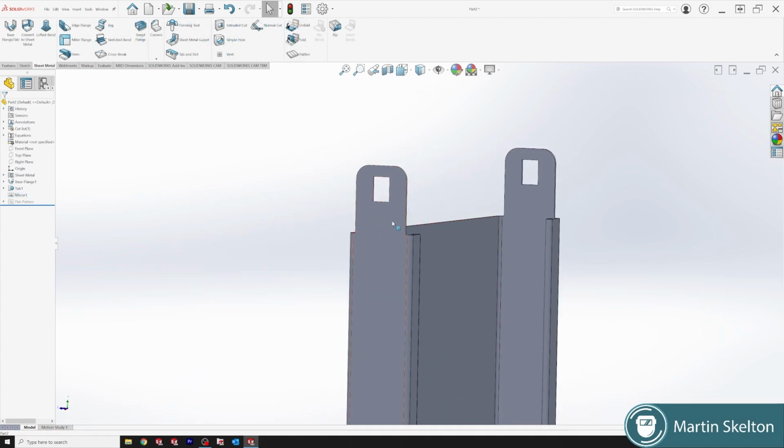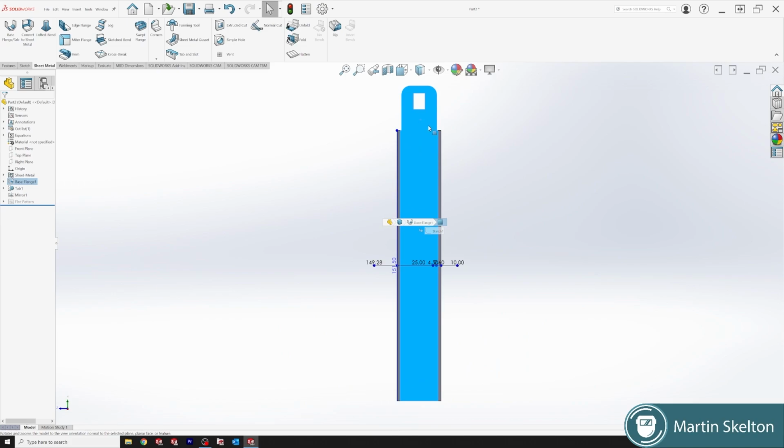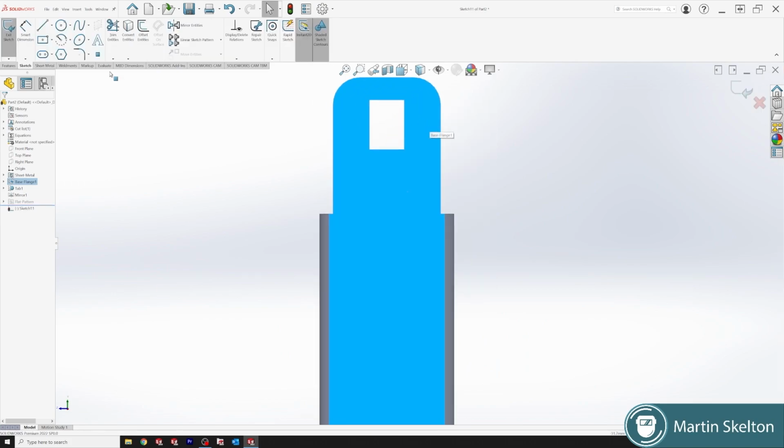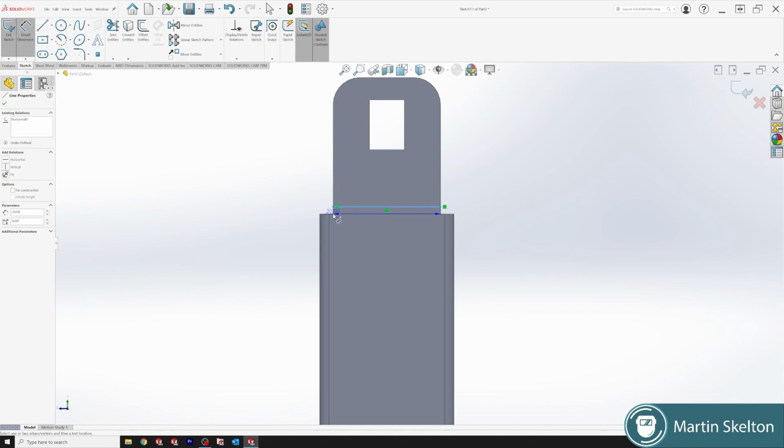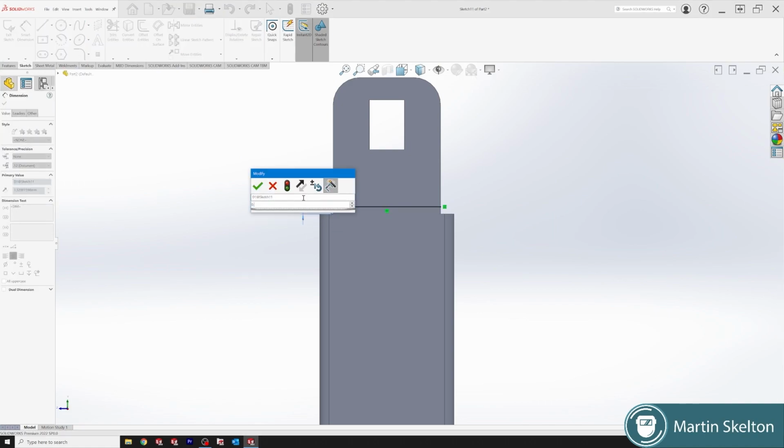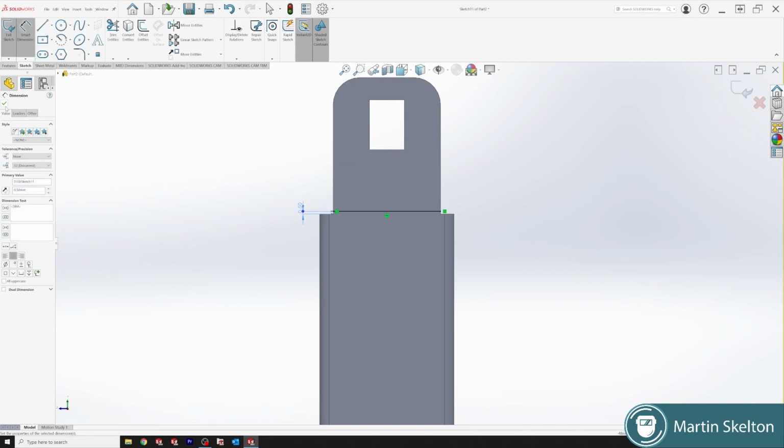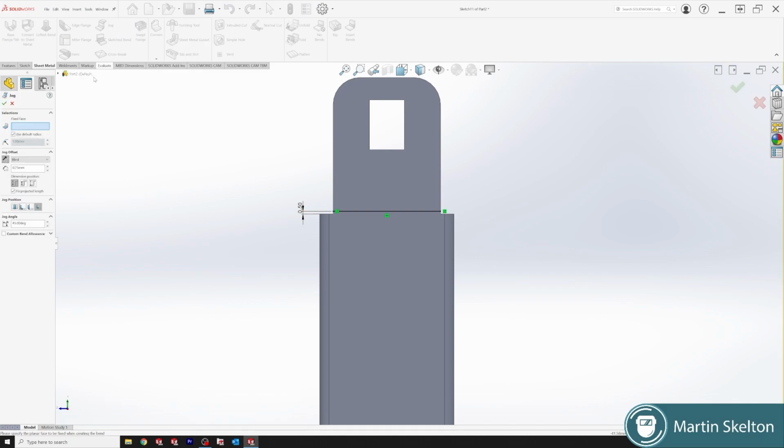Okay, so we start now with our jog. Click our face, right click, sketch. We take our line, draw from one side to the other side, close that line. We put a dimension of 0.5 because obviously for the jog feature to work, it needs to press out. Sheet metal, we're going jog. We are putting a 45-degree jog, 0.75 in thickness, and we're changing our default radius to 0.75.